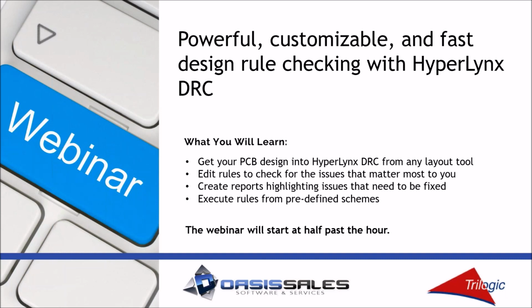So today we'll try to cover how to get your PCB design into HyperLynx DRC from any layout tool. HyperLynx DRC can bring in ODB++ files from most major CAD vendor tools. Then we'll talk about how to edit these rules in HyperLynx DRC to check the issues that matter most to you. After we run those rules, we'll be able to create reports highlighting the issues that need to be fixed that include details about each issue that has been found.